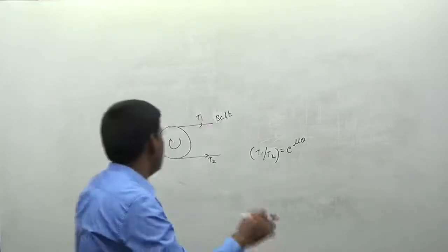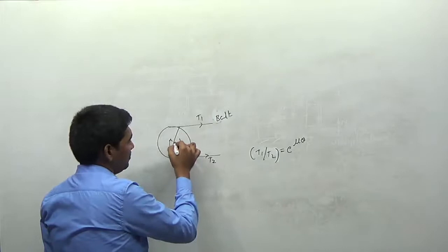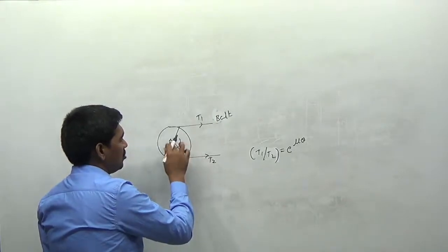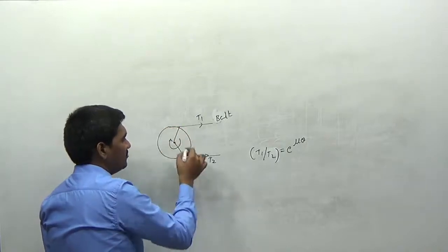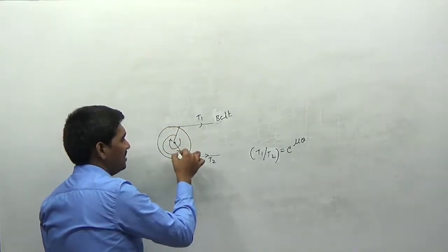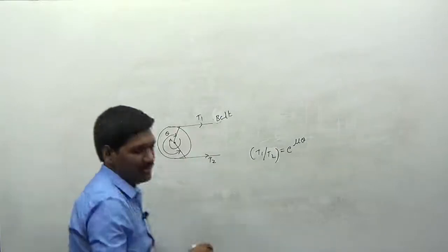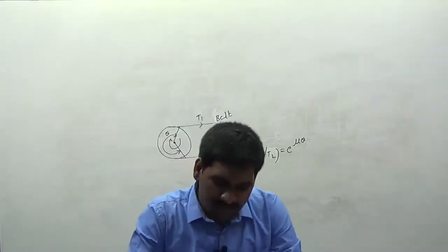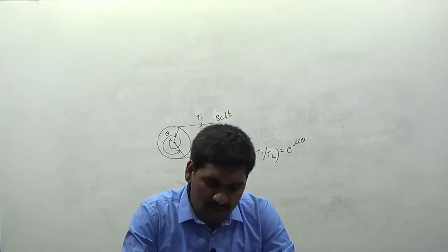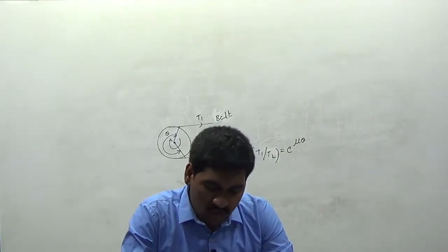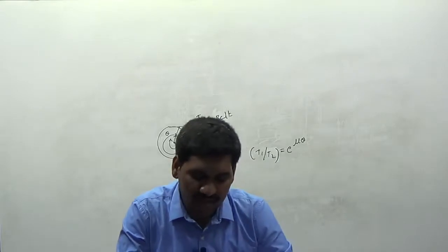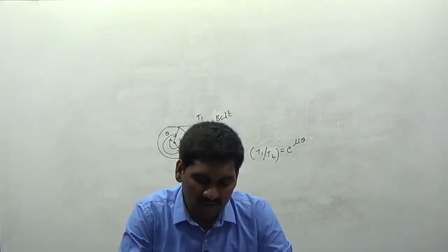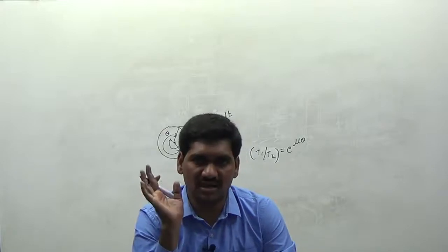Now you can observe here, this becomes the contact angle. So this is called the total contact angle, right? Along this total surface, the belt is covered. Therefore, I can say this total angle is equal to the lap angle generally, and I can call this angle theta here. Okay. The first option is proportional to the product of the coefficient of friction and lap angle. Second, an exponential function of the product of the coefficient of friction and lap angle. Third, proportional to lap angle. And the next is proportional to coefficient of friction. We don't have any proportionality here.